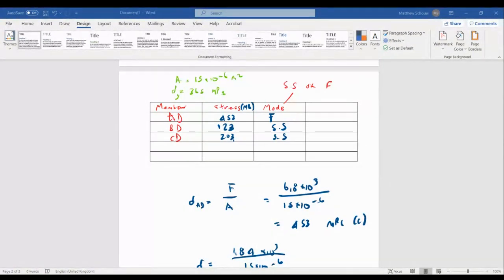Increase the area of what? Can you please be specific? You can increase the area of member AD. Yeah, fantastic. Thank you, Zach. And then what's the other thing? What's the last one? Maybe then we shouldn't use a 9 kilonewton load. We can reduce that load, obviously, to maybe 8 or 7 or 5. Maybe our 3D truss is not designed for that particular purpose. Those are 2 answers I'm fairly happy with here.